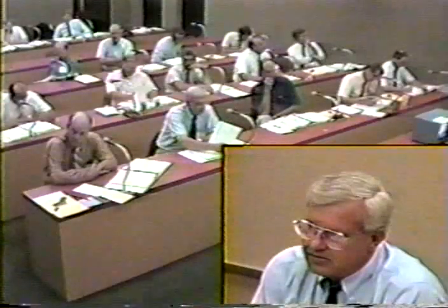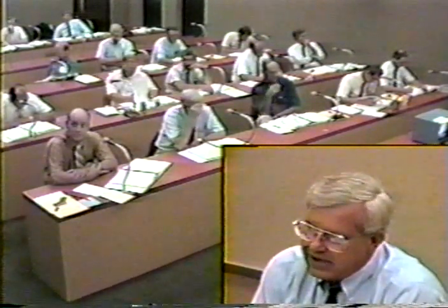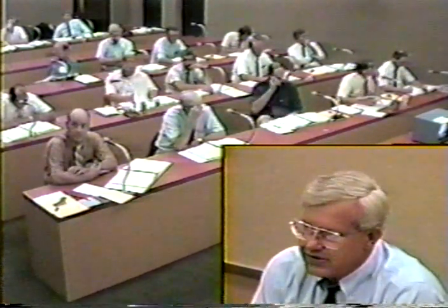Maintenance will not be doing the subsurface investigation to decide whether the drains need to be installed, but they play an important role in keeping things clean. In most installations, you would have a piezometer or an observation well in. Maintenance could read that, keep the data on it, and keep in touch with the geotechnical staff in the state.